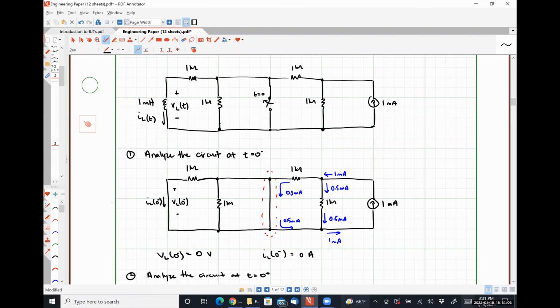So the circuit that we're actually working right now is still a first order transient analysis problem, but it's what's called a driven problem. And what I mean by that is it's starting with no source connected to the inductor, and then we are effectively adding a source in. And that's going to behave in a particular way that I absolutely intended to talk about on Friday. But today I'm trying to talk about what are called natural response problems where the sources are taken out. So to correct my mistake here, let's change the direction of the switch, okay, before we unpack a bag of worms that I'm not quite ready to talk about here.